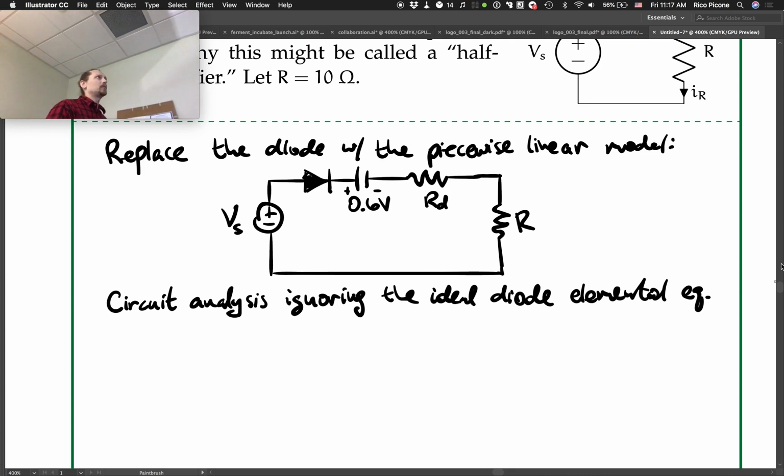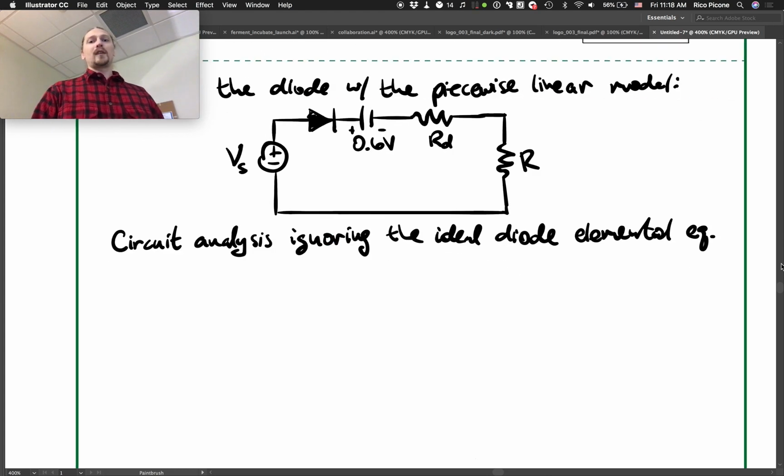There are some people who teach this method where you assume the states and then draw your circuit fresh and then do the analysis, and then assume a different state, draw your circuit fresh, do the analysis, but that's a lot of extra work. So I think you should do the analysis once and then make your state assumptions, which is essentially just adding one equation for each diode. So that's what we'll do. So we'll do the circuit analysis.